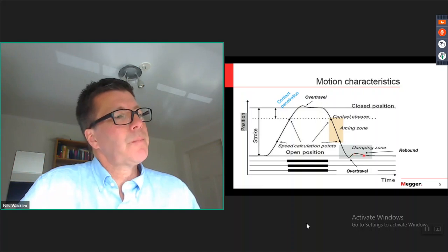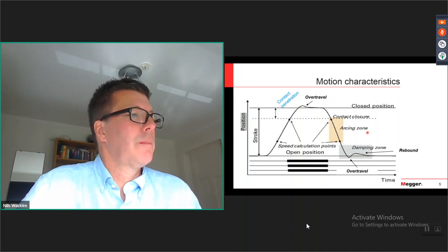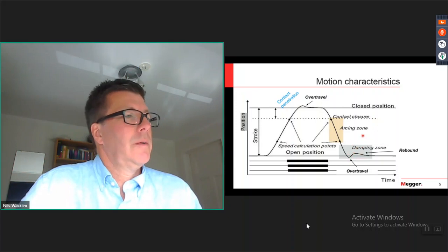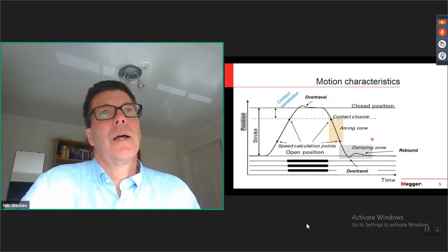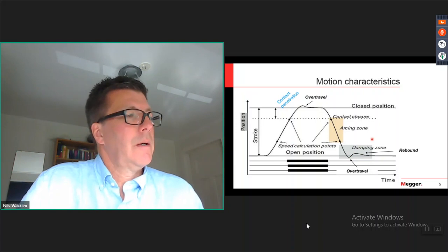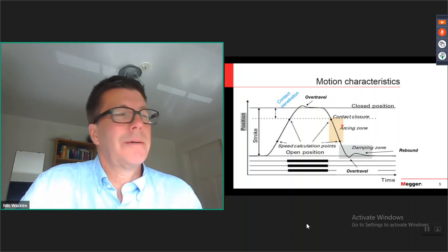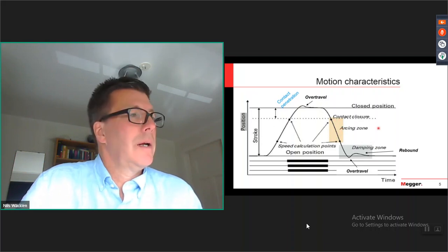But the rebound here, as I said, if the rebound is huge, like it goes up all the way to the half of the stroke, then there is a risk of restrike. Since also the gas inside, after an opening, is a little bit ionized.